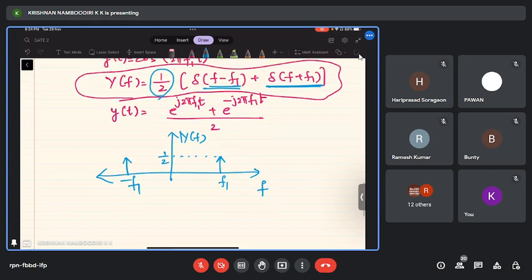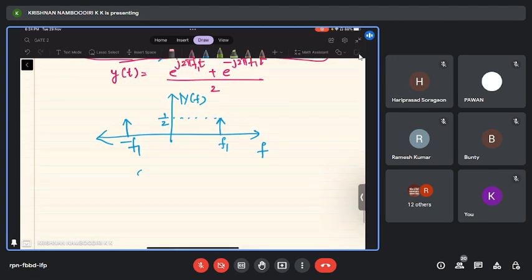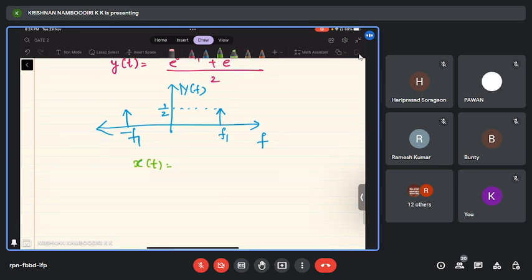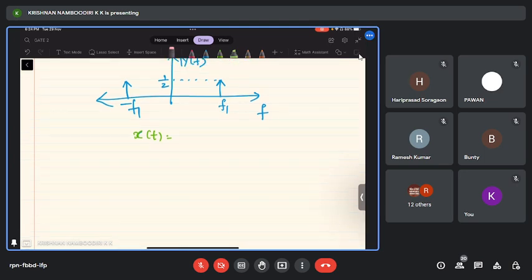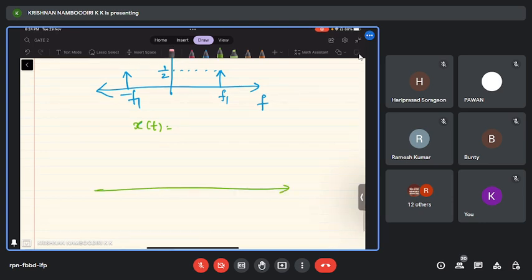Okay. Now the signal x of t is given as the sum of two cosine signals. One has frequency 5 hertz and the other has frequency 15 hertz, right? How does the spectrum, the magnitude of X of f, look? It will look like this. At 5 hertz and minus 5 hertz, there will be peaks corresponding to cos 10 pi t, and at 15 hertz and minus 15 hertz, there are two other delta functions corresponding to the 15 hertz cosine component, correct?